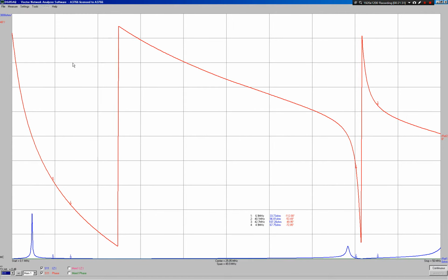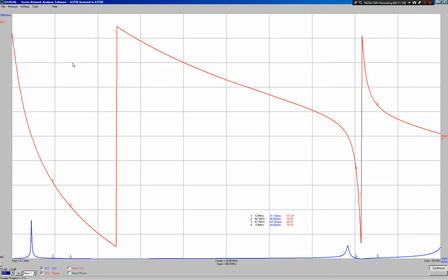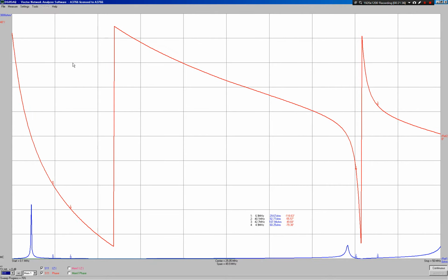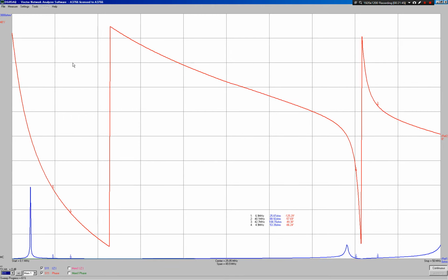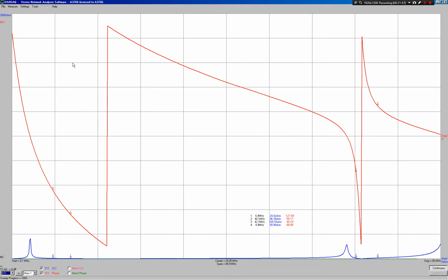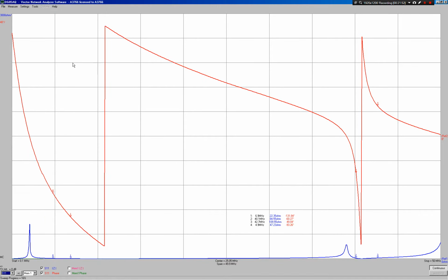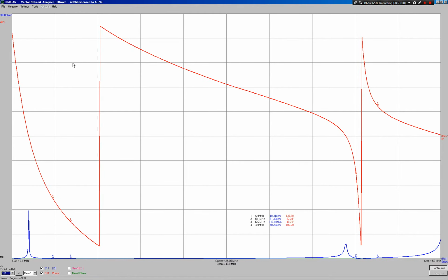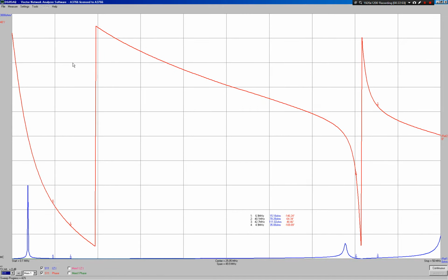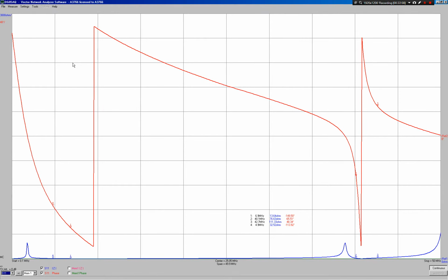As it keeps marching down. We'll do a narrowband scan of this also later so we can see more accurately what's happening at the lower end. Still winding it down. Okay, we're probably at around about 600 puff now. We're about halfway over the adjustment range of the variable tuning capacitor.